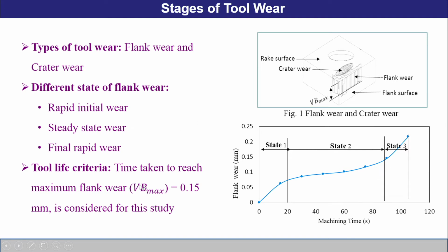Now, in general, if this VB max is 0.3, then it is assumed that the tool life is exhausted, and you need to change the tool.